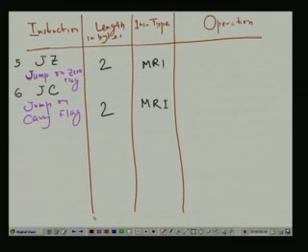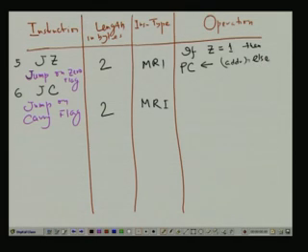here one condition is checked. For jump on 0, I have to check whether the 0 flag is 1 or not. If z equal to 1, then program counter is the address, else PC is PC plus 1. That means if it is 1, then jump to a new address and that value is given here. So, that address is loaded to program counter. So, that program counter always contains the address of the instruction to be executed next.